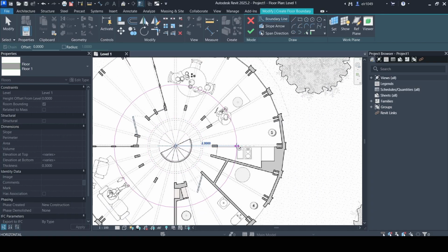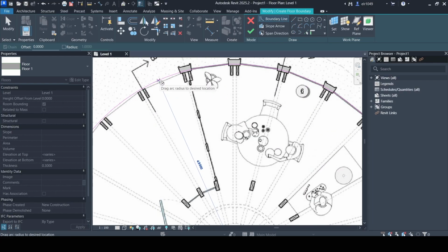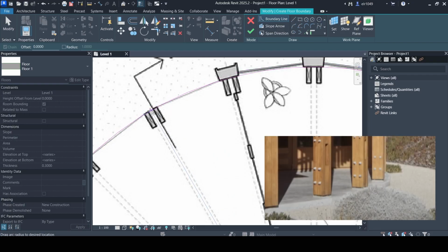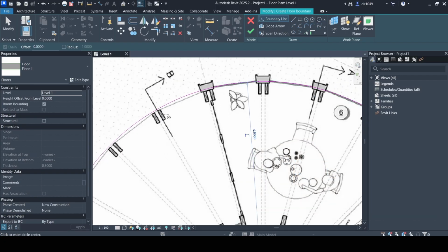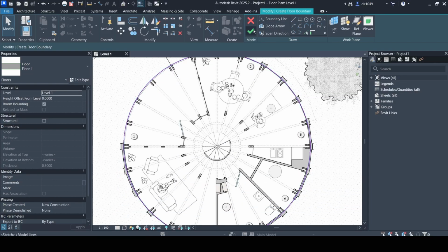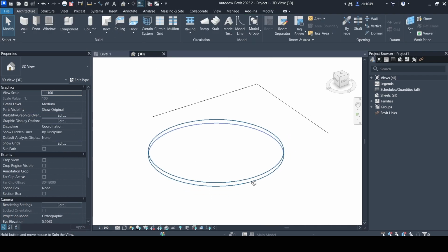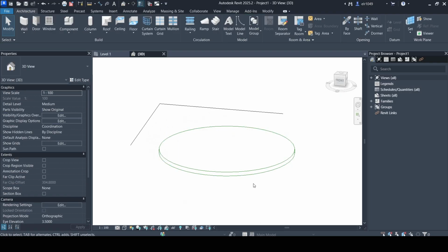And we're going to drag it out to the bounds of the building. I'm going to go up here because we can actually see where the foundation should be. And I'm actually going to push it just a little bit past these posts because I see in the reference images that these posts have a little bit of the foundation poking out beyond. Then I'm going to click the check mark to finish our foundation. Let's go to the 3D view to check it out. There is our foundation. And now we can move on to the topography for our site.